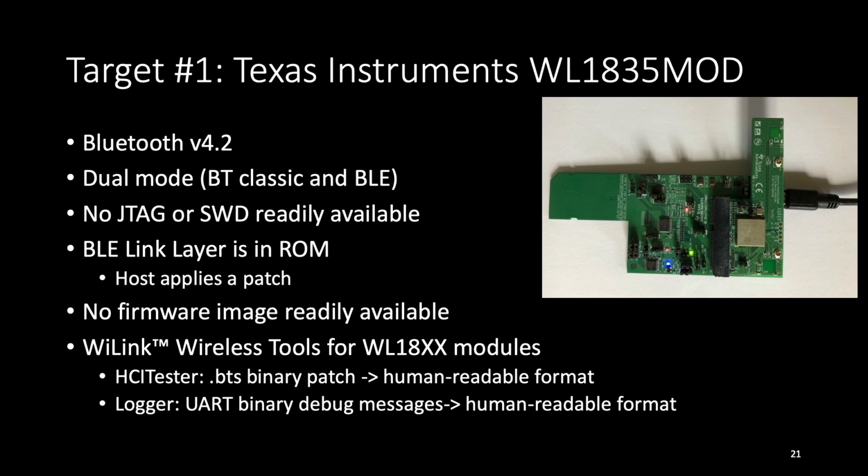If you use the HCI tester, this tool will translate this binary format to human readable strings. In the case of the logger, when I look at just the UART message traffic, the UART messages are in binary format. And if you attach this logger to the UART, it will display log messages as strings.